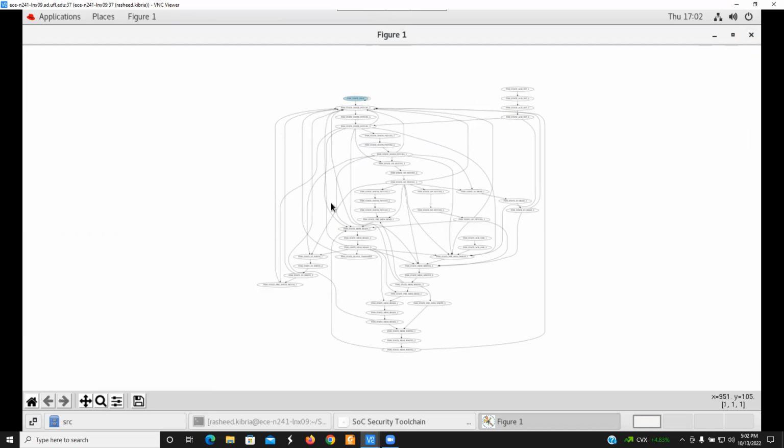We have so many states and so many state transitions. The state transition graph is very complex, and as a result, this STG was not extracted by using Intel's Quartus. RTL-FSMx is better in this sense because it can analyze very complex RTL designs and also provide you the FSM extraction report within just a few seconds.